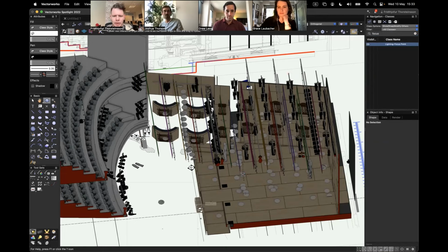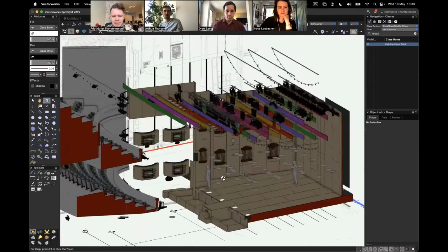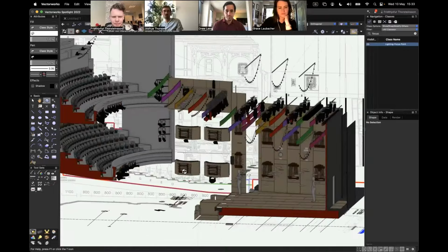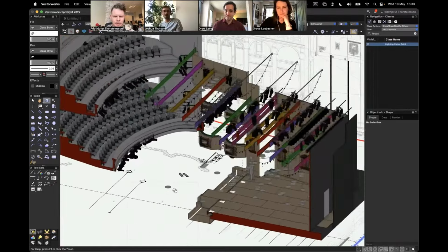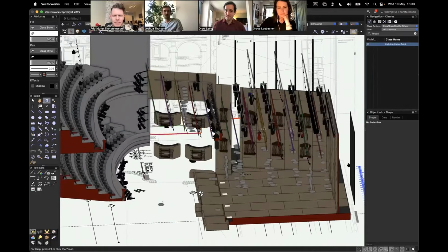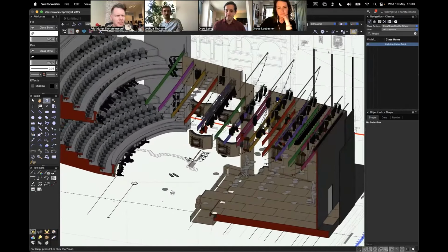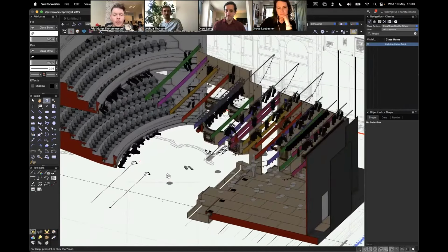And at one point, all the lights stopped pointing at the focus points, and I had to go through quite some trouble to get them working again. But apparently this is some sort of a bug in Vectorworks. All you need to do is re-import all the lighting instruments from the online library and then refresh your instruments. I wish I'd known that before I replaced all of them in the drawing.